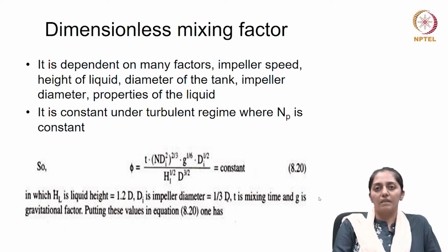In that we were discussing that there are various scale-up criteria, where yesterday we discussed in detail the power per unit volume scale-up criterion, which is equivalent to considering equivalent mass transfer characteristics at both the scales, and then the volumetric mass transfer coefficient, which demonstrates equivalent oxygen mass transfer characteristics at both the scales.